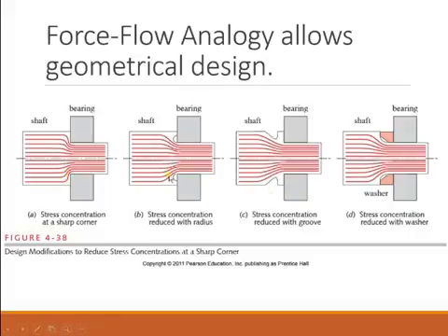And yet all three of these other ones, although they have very different designs, are going to accomplish a very similar result. Just from looking at them, I probably would choose this groove approach, which is not intuitive at all. You would not think that taking a flat corner and removing material will actually decrease the maximum stress.